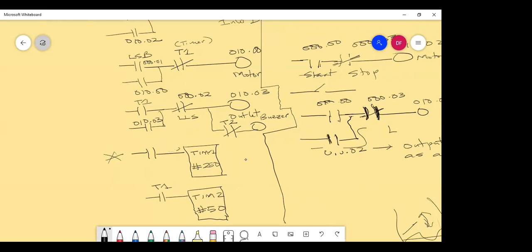Change that switch. Right. So we didn't use that. We didn't change the switch physically. We just changed what we use in the program. Level switch B started the motor, so we just use the motor as the turn on. Now when the motor turns on, it stays on. So level switch B started this, so we just use this as our turn on for the timer. And once the motor turns on, because it's latched, it stays on.